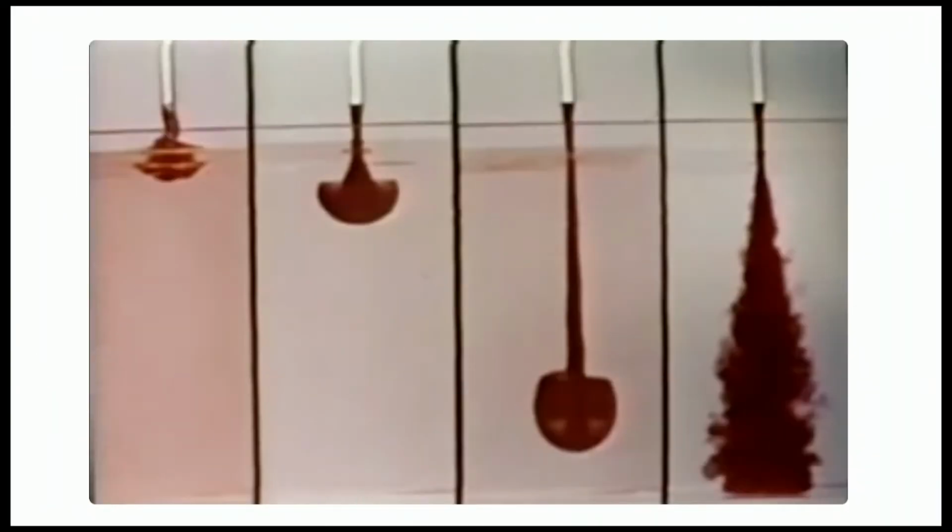So the cases that you saw in the video can be generalized in this picture. And here, the Reynolds number increases as you go from left to right. So of course, the case on the very right of this figure is an example of turbulent flow. But we are going to talk more about the cases which are towards the left of this figure. So the first one, where the Reynolds number is very close to zero, that is a classical example of Stokes flow. So we are going to restrict ourselves to the cases where the Reynolds number is very small.